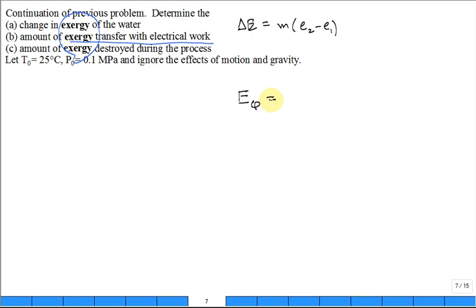Yes. So if I had this much heat transfer, I'd multiply by 1 minus T dead state over the boundary temperature at which the heat was transferred. And that would be the amount of exergy transferred with the heat. True? Can this ratio be greater than 1? This fraction. No, it's less than 1. It's a percentage. It's a Carnot efficiency.